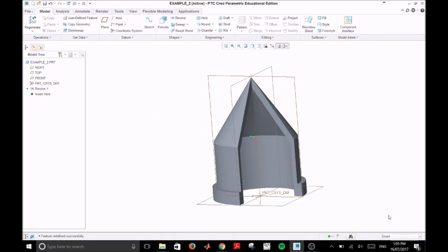At this point, it is now worth practicing some revolutions by yourself, remembering that to create one, you need to reference a datum plane and an axis of revolution. It also requires a slightly different thought process in that you can work in terms of diameters. As a final note, you can also remove material using revolutions, in a similar way in how the holes were created with our extrusion video.